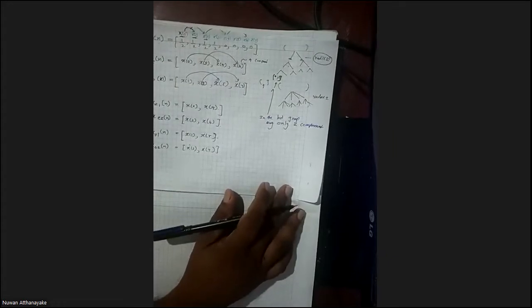Excuse me, sir. Yeah, tell me. Sir, you said that we have to zero pad when there are only 5 components given. Yeah. Is that because this is an 8-point DFT? Yeah. To perform the 8-point DFT, you should have 8 components. Okay, sir. Thank you, sir.